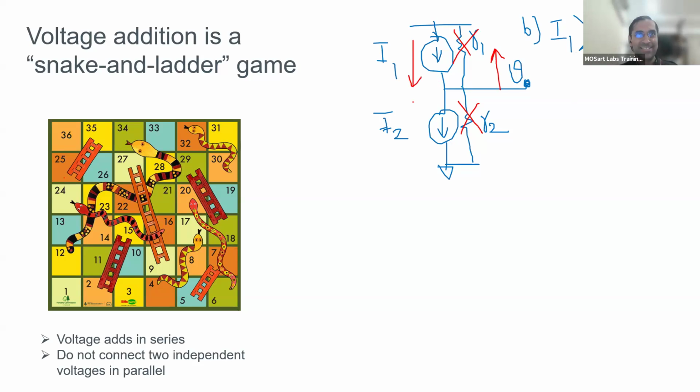Strange thing with current sources. You try this experiment. First I1 will pull it up to VDD. It will reach a point where it goes beyond the voltage compliance of this current source. The voltage becomes so high that it will break I1. I1 will stop working as a current source and now becomes almost like a voltage source with an impedance. Because the bottom side can sink only I2, you will effectively sink only I2 current. Very strange and interesting experiment. You can try it out.